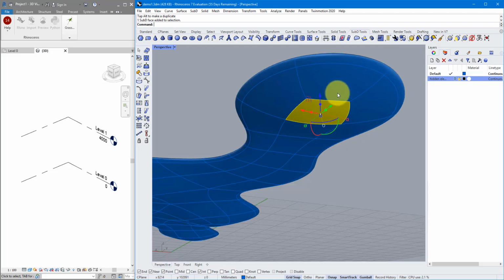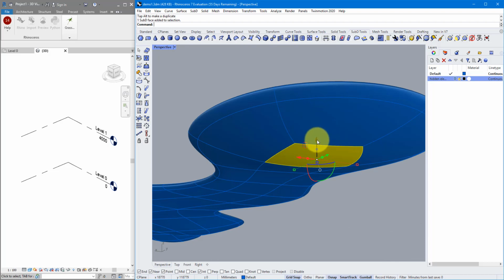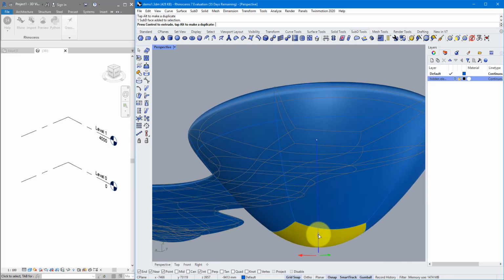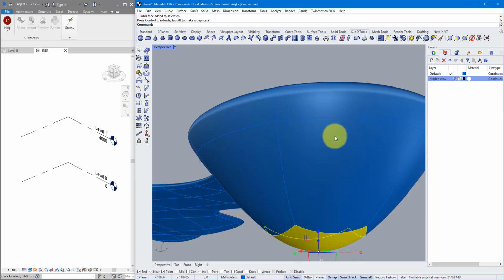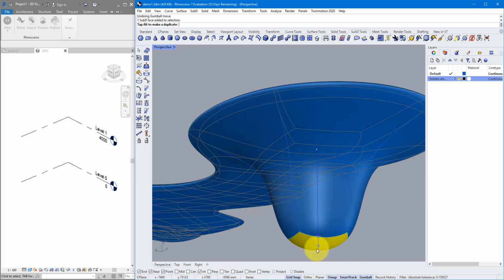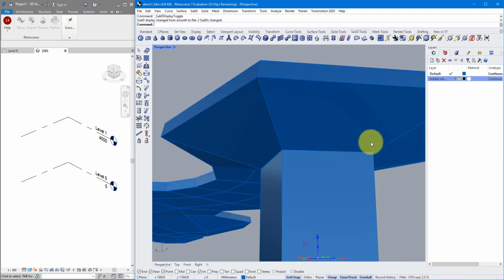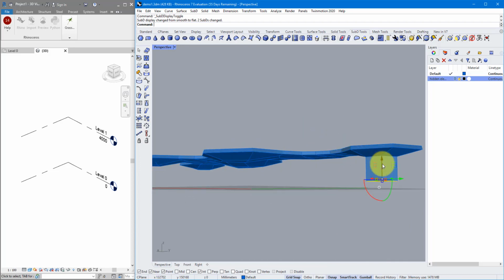This is where we need to pay close attention to the gizmo. As you can see here, if I just drag this one down with the arrow, it's moving down and it creates this very chunky bulk here. So let me undo this, select it again, and now instead of using this arrow, the whole thing, I should only click on this little dot on that arrow itself. So now when you see moving it down, the thing has been extruded instead of moved. It's clear to see if I turn back to the mesh representation. You can see there, it was extruded, not moved.